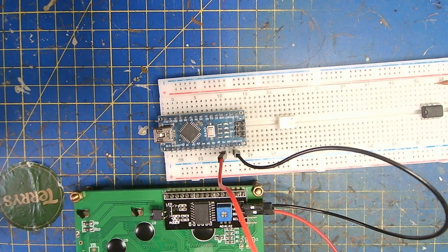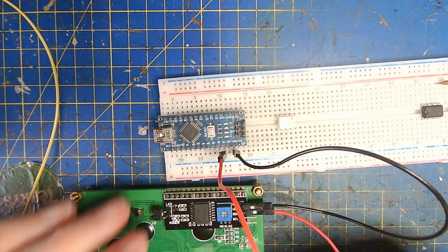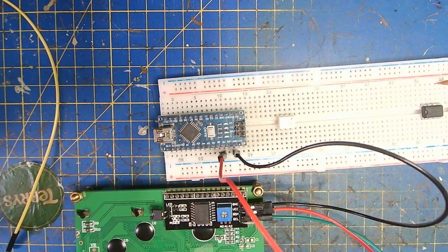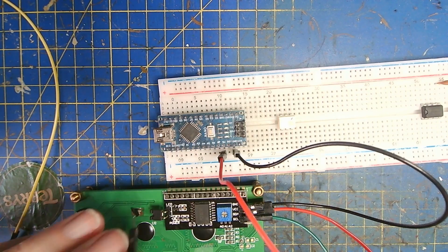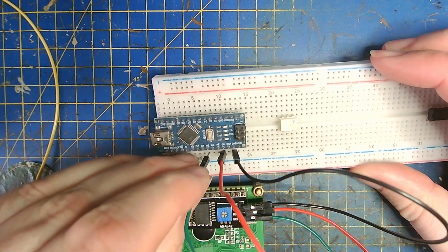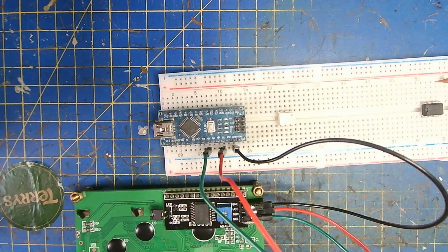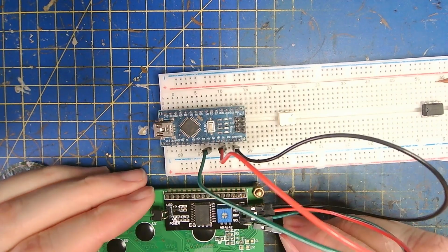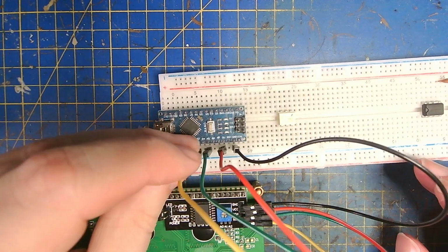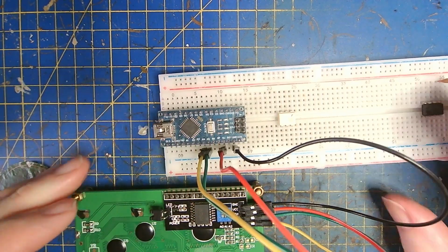And we need to connect these two. Now, if you're using an ESP32, you can connect these to different pins. On the Arduino here, I've got the SDA pin, which is this one. This goes to A5, which is, memory serves, let's have a little look so I can see what I'm doing, that one. And then I've got SCL, which goes to A4. Now, on an Arduino, those are your I2C pins. So that's connected.